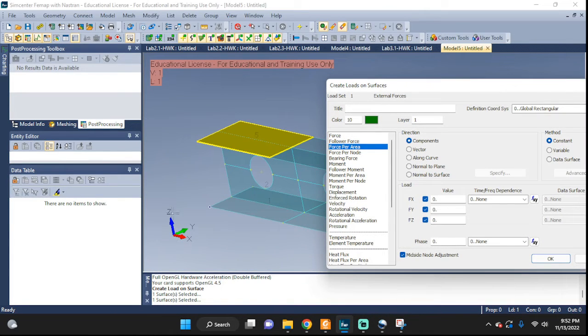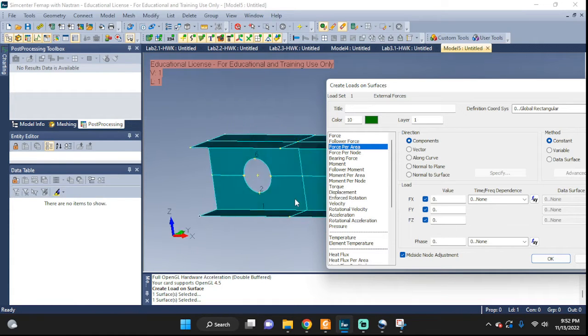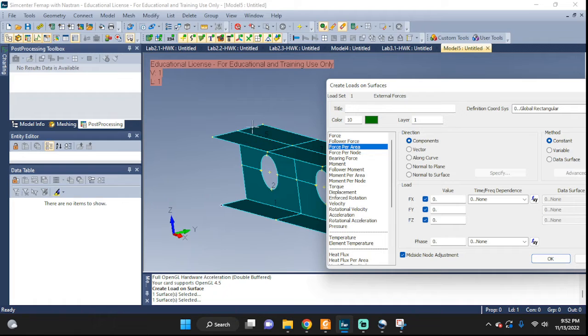Let's see, we are in the z direction, so I'm gonna put it in the negative z, right? That's what we need. Yeah, negative z direction. Or actually let me put it in a positive z, so it's pulling on this surface z right here. I'm gonna put it there. We're gonna put, let's say, 10 newtons or 10.